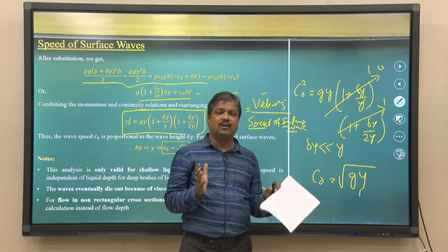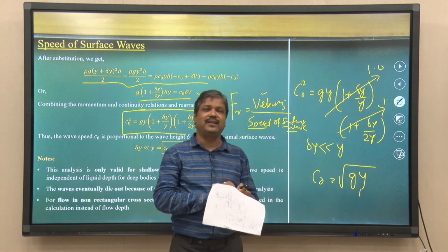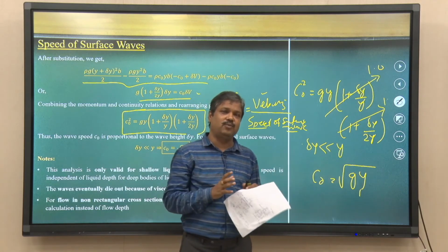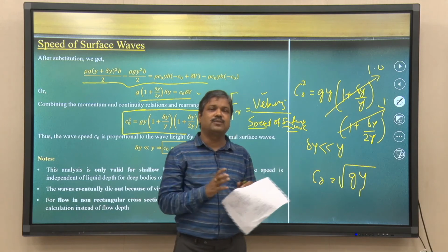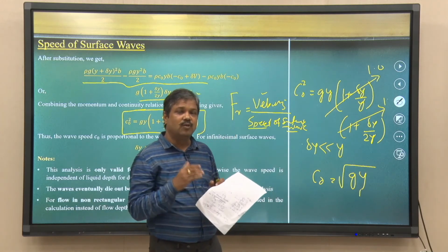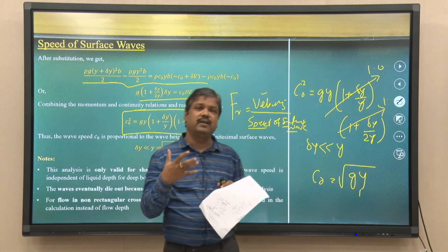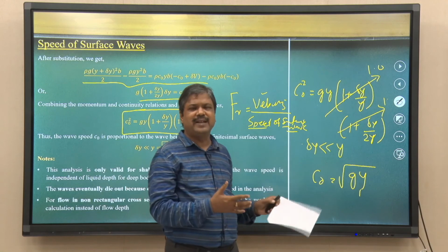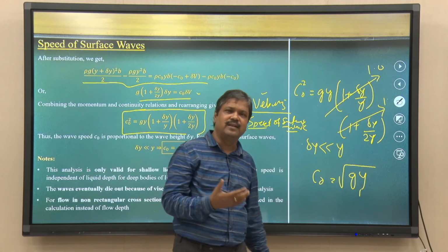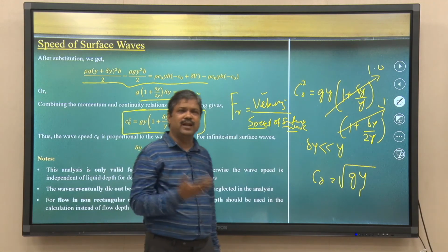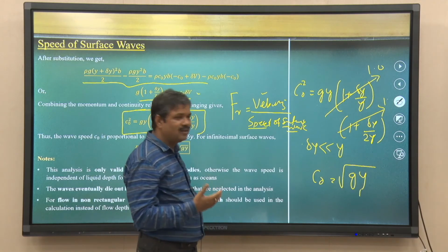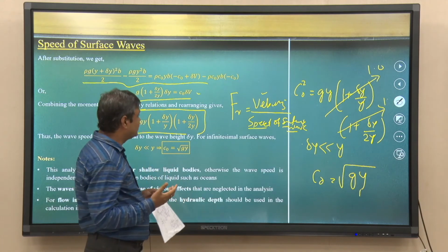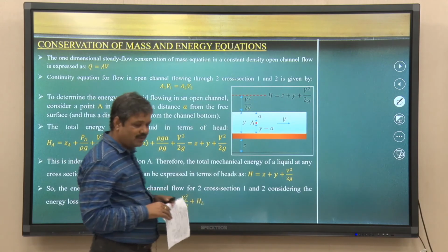So, that is the way you try to understand it; there is a physics behind that to classify the flow, other than the very simple way of defining the ratio of inertia force to gravity force. In open channel flow, where the speed of the surface wave matters to us, we look at the ratio between the velocity and the speed of the surface wave. More detailed derivations you can look up in Sindel Simbala books, or in the FM White book. I am not doing the line by line derivations, but try to understand the physics of these problems.